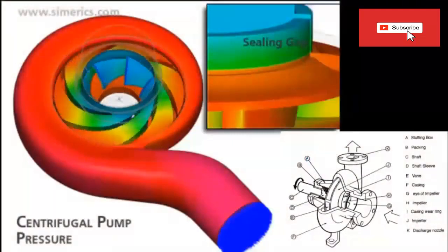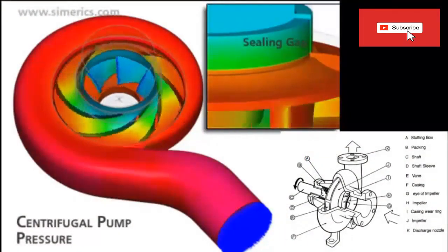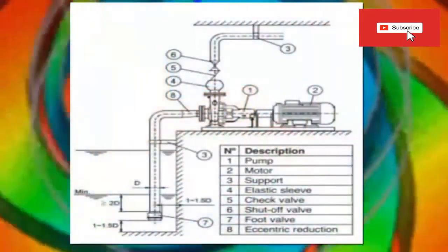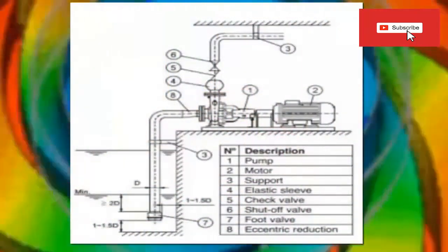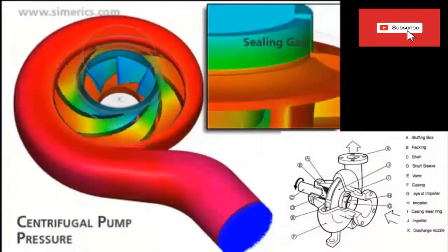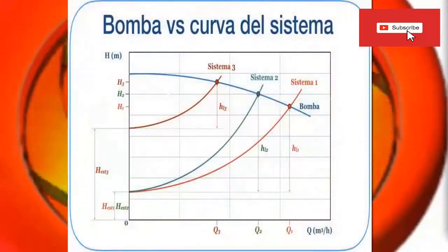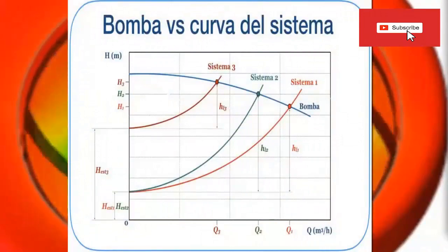Nine: The installation of pumps requires accessories such as valves and filters. Ten: Place the minimum of accessories in the pipe that enters the pump through the center, or suction pipe. Eleven: The curve of a pump allows us to know its behavior at different water flows.